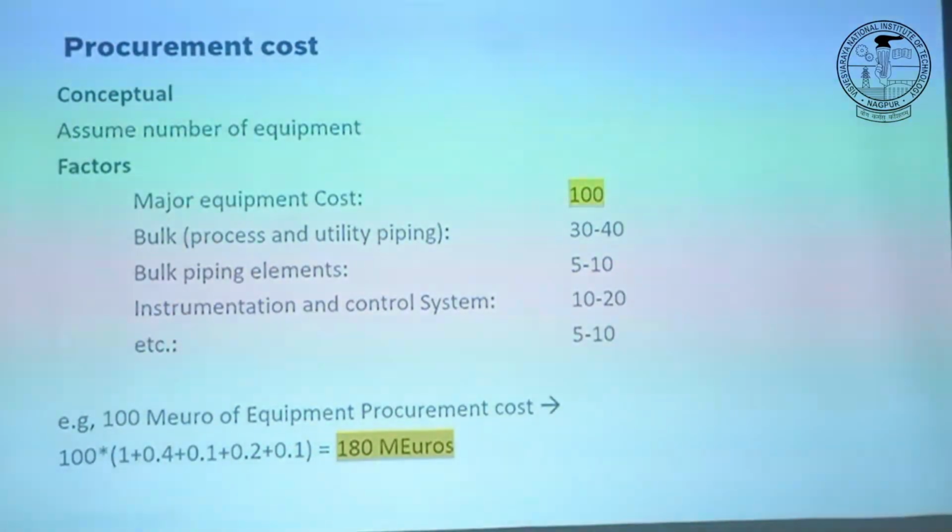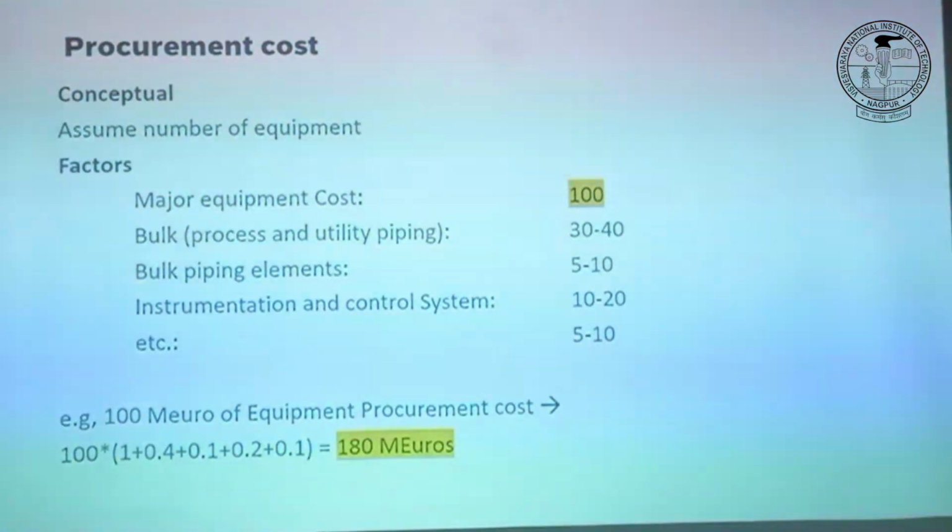So far we saw a bottom-up approach. Means you say, I have equipment, that's my weight, that's my factor, and slowly I go up and then say, that's my 37.4 million total capex of the plant. That's bottom-up approach. And there is another one, top-down. You say, I apply factors now. So for an example, if my equipment cost is 100%,